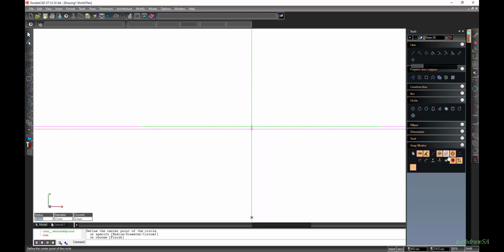So what we want to select here as default, and this is for our syllabus, everything that we will always select, is this vertex, which in DoubleCAD is called endpoint. We want that option, and we want the middle point option always selected. I'm going to deselect the center option by clicking on it, so it's gone. I'm going to deselect this quadrant point.